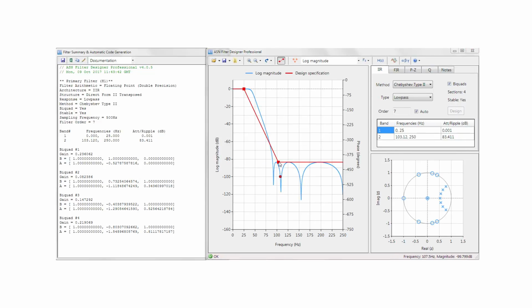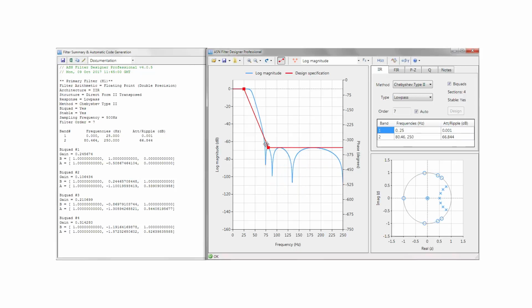Okay, let's now return to our application. The requirement is to attenuate our power line harmonic frequency, so in this particular case 50 Hz, 100 Hz and 150 Hz. In order to accomplish this, we need 3 nulls. Now let's see if we can reduce the filter order somewhat, such that it's a much more efficient implementation.